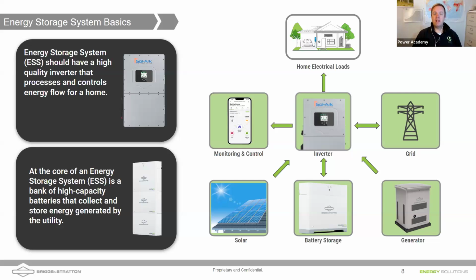I would also mention that we see a lot of people adding batteries to existing solar systems. A lot of times those existing solar systems have microinverters or string inverters. They are by design supposed to shut off with the loss of grid. Well, using energy stored in that battery, we can create a grid form, right? The inverter can be a grid forming inverter, and it will create that grid, tricking the Enphase or the SolarEdge or whatever string inverter you might have to continue running, and then using frequency shifting, which Nathan will talk about in a minute.